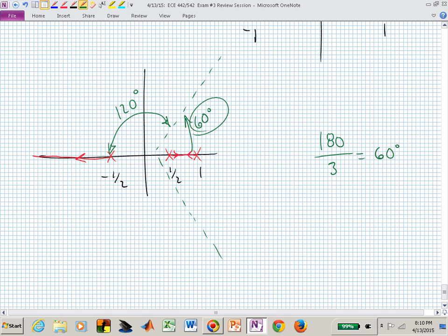How's that? Is that clear, sort of? Do you get the idea? We'll talk about those centroids. But what's going to happen is these two are going to come together, and this one's going to go up here, this one's going to go down there, and this one's going to march off to minus infinity. Is this system ever stable based on this picture, root locus?